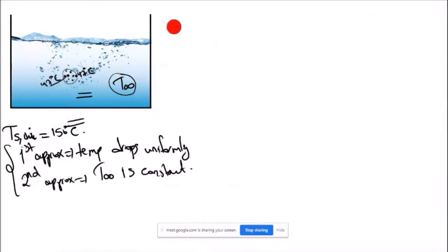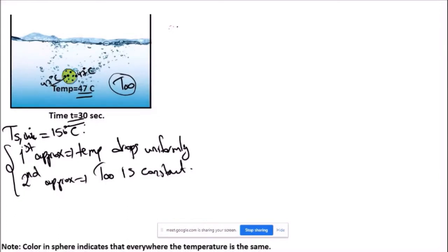And we have said here it is dominated by convection. Dominated by convection means that heat loss from the body is by convection. There are no radiation effects. Okay, it is zero-dimensional, with no change of temperature with respect to location, and it is transient because the temperature changes with respect to time. As time passes, temperature changes, and it is also a convection-dominated case because you have heat loss only by convection, CV. Okay, good. There is no conduction here.